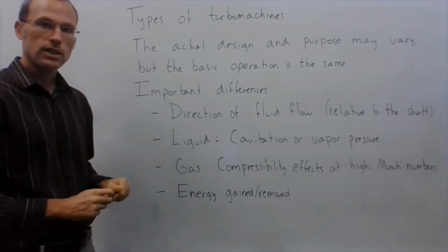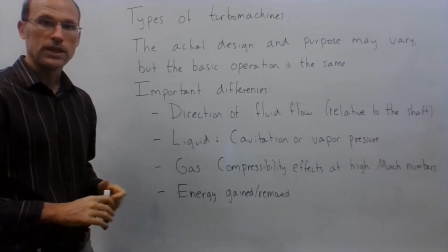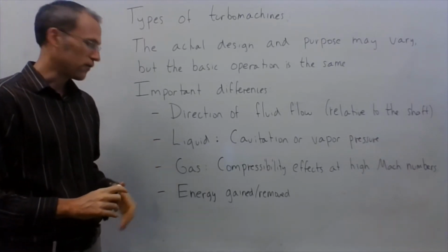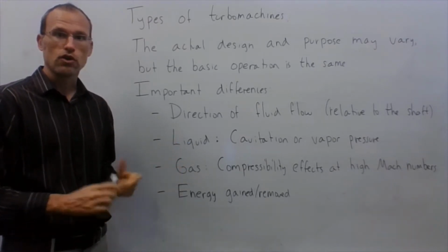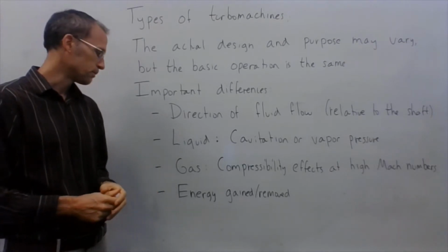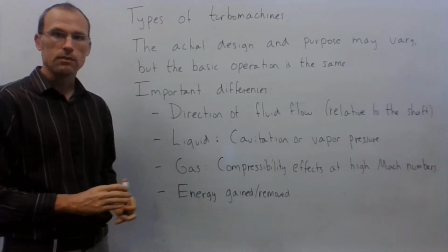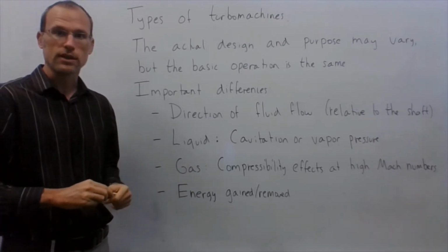The other distinction is whether it's dealing with a liquid or a gas. You have different issues related to both. For liquid systems, you have to worry about cavitation or vapor pressure. If there's a really large pressure difference, you can end up having cavitation on one side, and that's not good. For gases, you could end up worrying about really high speed effects, Mach number, compressibility, things of that nature.